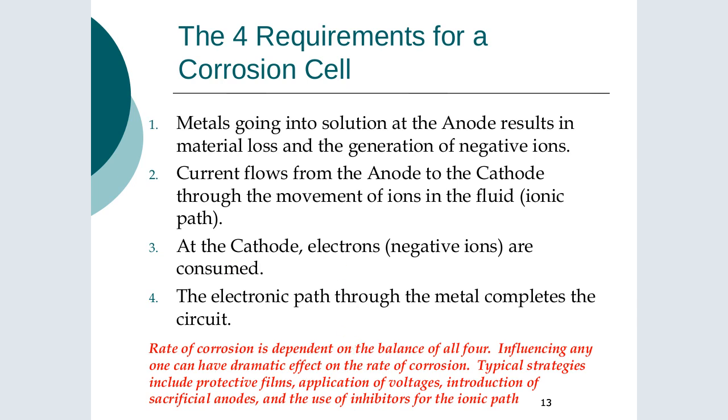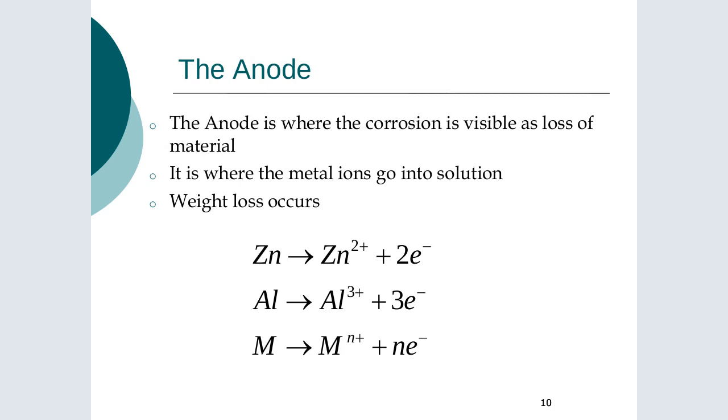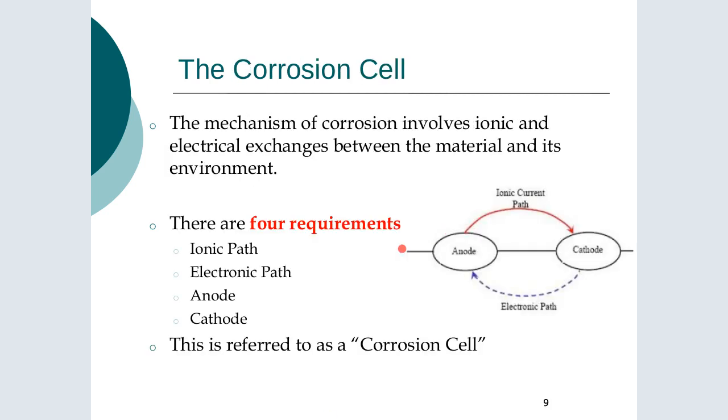Now, something that's also important to mention, and I mentioned it earlier, is the use of these protective films. If we go back just to the slide here. If we put a coating over the surface, then we shield it, or we have a passivating film, for example the corrosion products forming that passivating film. Either we painted the surface or did something to isolate the surface from the environment. So ostensibly that will sort everything out and really kill the rate of attack. In fact, in principle, it stops it completely.